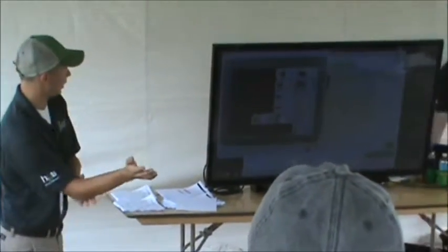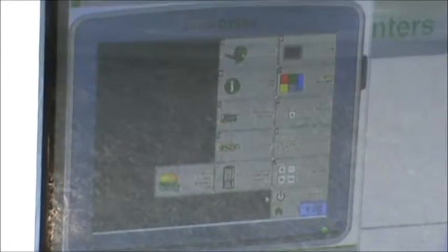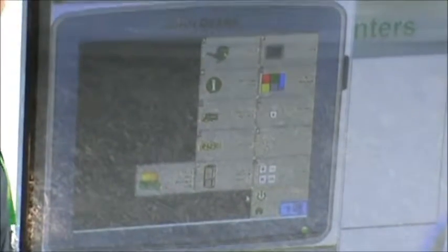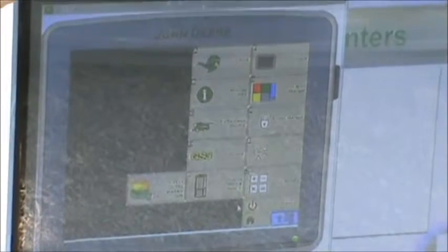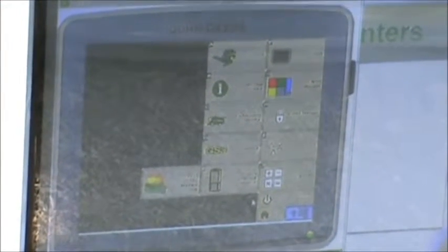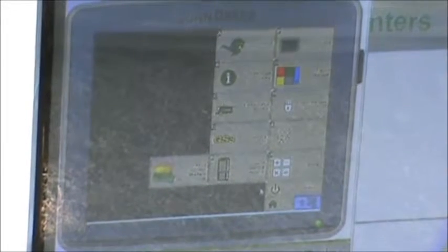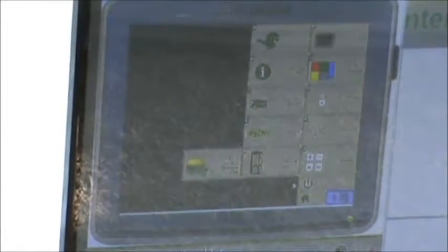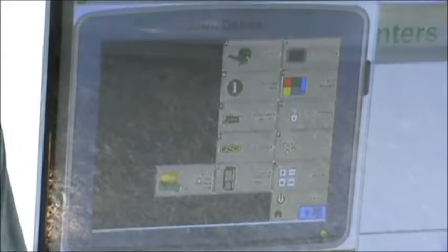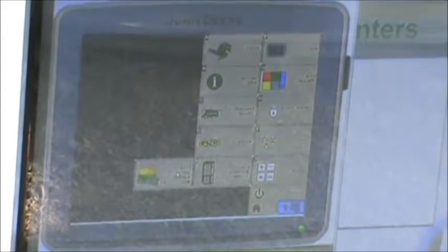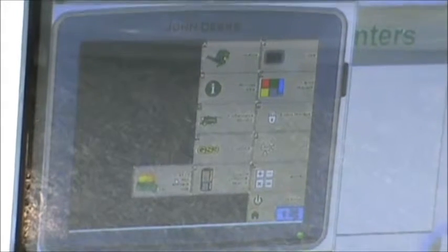When you first start up your display, it'll ask you to calibrate TCM, and then periodically it'll come up with an alarm saying TCM calibration required. We want to recommend that you guys do this as much as possible, because with drift and stuff like that, it's really important to make sure you keep calibrating. Do it as often as you can. Yep. If it's something you guys can get into every day or every other day, that would really make your information more accurate.